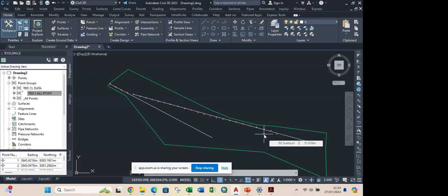You can pick the coordinates where you have critical curves that you can't avoid on the road. It must be a curve here, it must be a curve here, it must be a curve. That will aid and guide you when you are doing the horizontal alignment of the road. So you know you have those critical curves that you can't avoid, and you put them on the road.